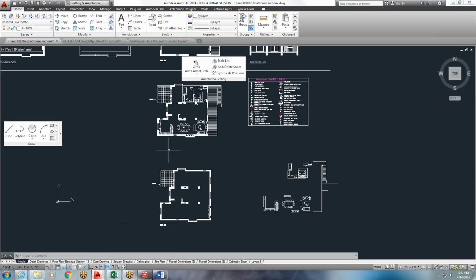They ended up being, the rise and run were such that if you were to take a step, it was almost 12 inches up. So every rise was 12 inches high. It had a pretty average run, but it was still impossible for anybody to get down and up naturally. So I went through and corrected that, and I want you to correct it in your plan.